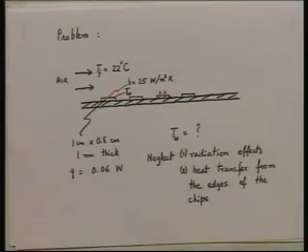If you have to take it into account, it is going to be a more complicated situation. So, it is a straightforward situation. First of all, before calculating T_w with the help of Newton's law of cooling, notice the value of 25. What does 25 mean? 25 means we have a typical value of h for forced convection to air. That is the first thing to notice. It is not a natural convection situation. We have a typical value of h which we will get with forced convection to air.